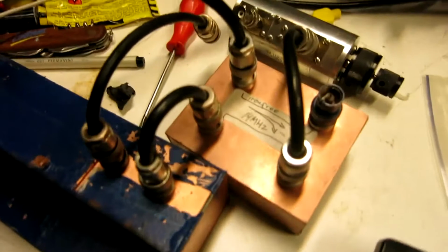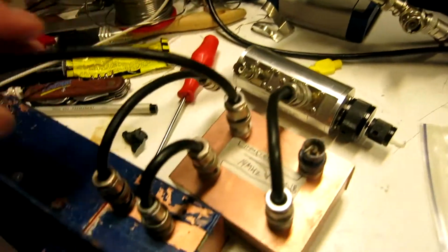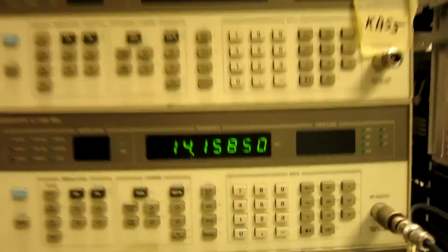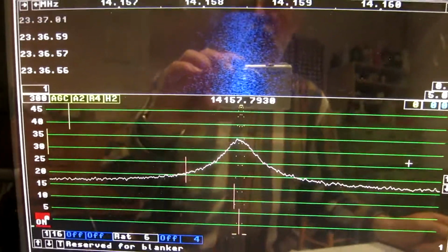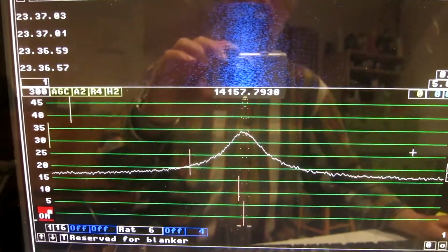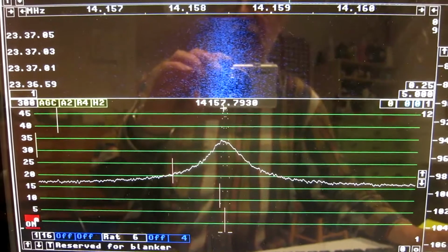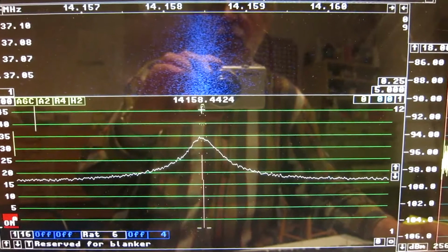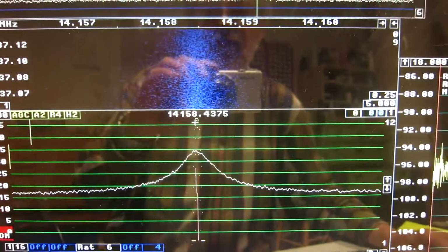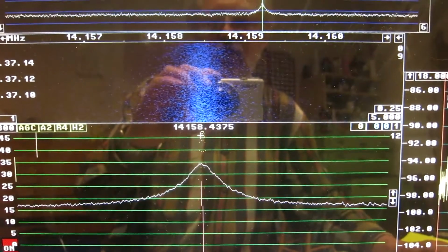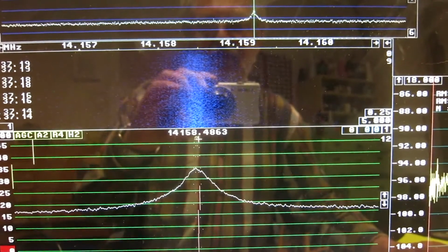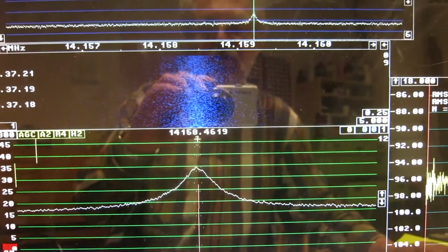I have disconnected the feedback here, and the input is connected to this signal generator here, and right now it's switched off. First I want to look at the noise floor. This filter that is applied in Linrad, I can probe for the 3 dB points about here, 437 Hertz to 486 about. So this is about a bandwidth of 50 Hertz.